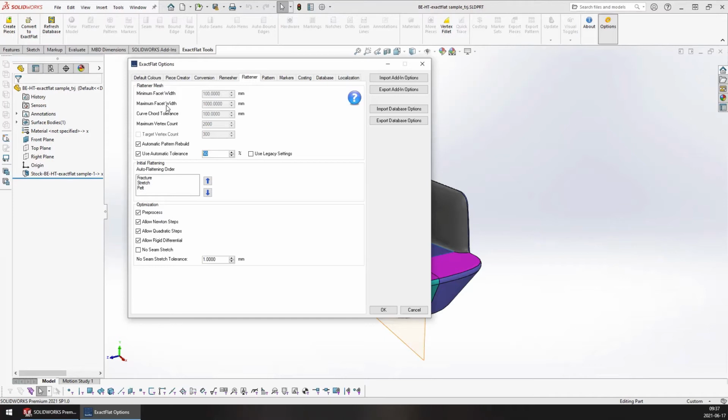But unlike the adaptive remesher, this does not scale with part sizes. So if you go from designing something like a watch, the meshing parameters you use for a part that size are no good for something the size of an automotive vehicle, a car, or a truck. If you make that jump and you use the same meshing parameters, now you're going to have millions of triangles in your mesh for the truck. So it becomes very cumbersome.